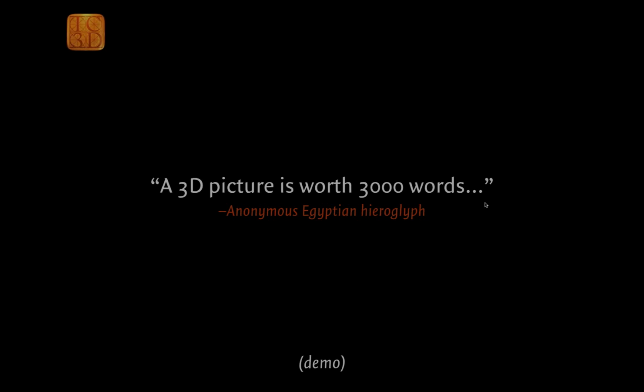You can actually move the lighting scene around the object. So if I create a teacup and I place that in my scene and I want to have a particular view on that teacup, then I can do that. I can place the object in a particular position. And then I can grab my light scene, and I'll show you in a second how to do that, and I can move that around. And that means that the lights that I have in that lighting environment will change position with regards to the object that they are lighting.